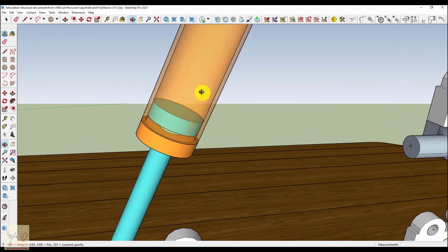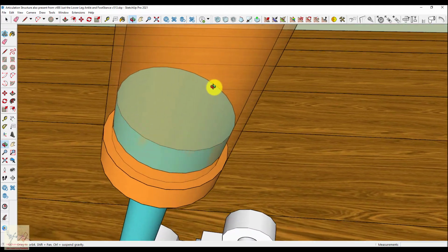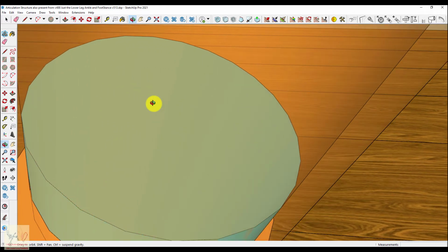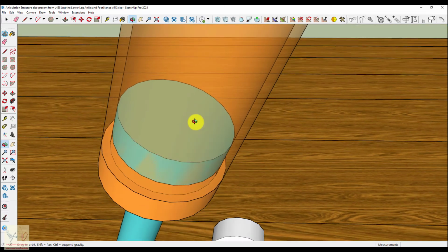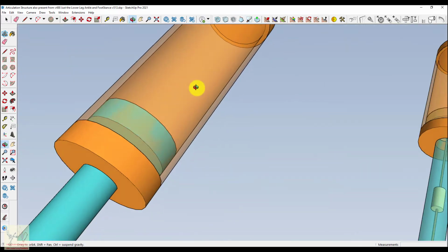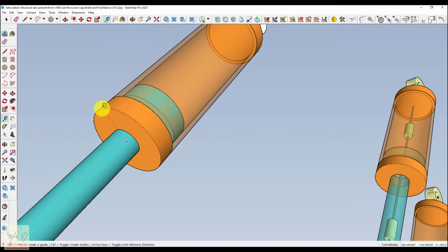But one of the things that we should look at is to go inside of this and see if we can measure. Let's just measure from here to there. So that's 2 inches in diameter, and this little blue piston is a little less than that, but the radius is 1. So pi r squared is pi times 1 squared, which is 3 basically. So it's 3 square inches.